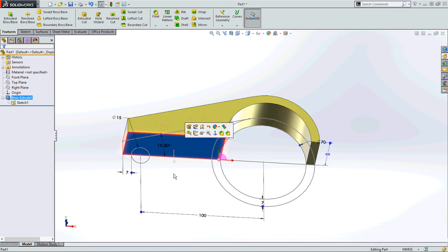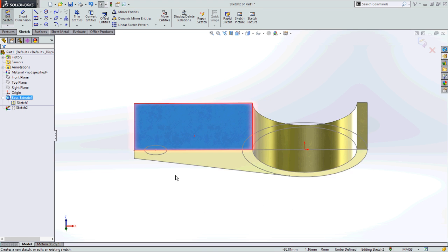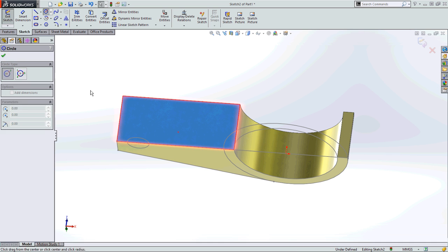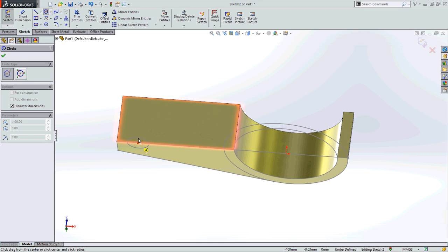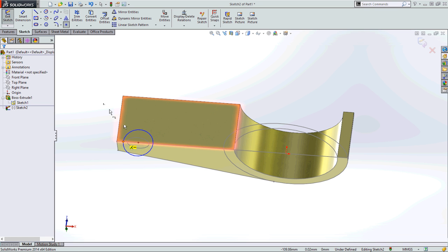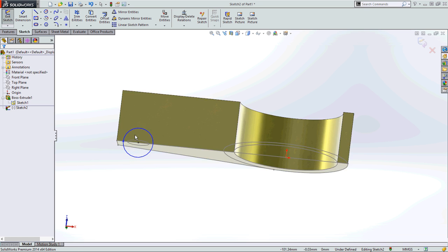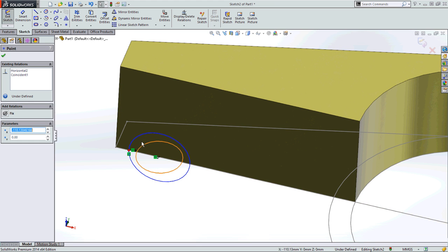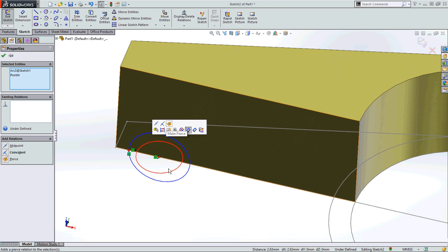So it's on this bottom face here, we'll create a sketch, and let's rotate that a little bit there. So create a circle, and I'm just going to snap to that. So when my first sketch changes, the location of this circle is going to change as well. I'm going to create a point on this circle right there. So I hope everybody can see what I'm doing here. Created a point here, and then I'm going to make that point pierce the circle in the other sketch.